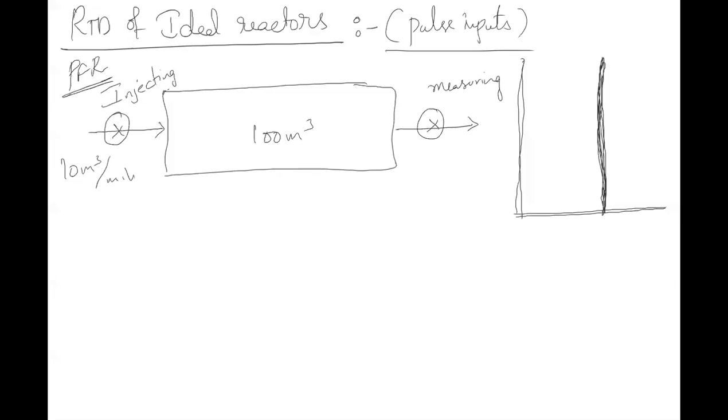What is a CSTR? Suppose the occupancy of the reactor is 10 people. At any point of time, that reactor has 10 people. The person who has entered with 100 red particles, immediately after he enters, will share those 100 red particles with everybody. So that is what a CSTR is. Equal sharing of the molecules on each plane is called a CSTR. No sharing between the planes is called a PFR. Now at what time will you get this peak in the PFR? Equal sharing is called back mixing, 100%.